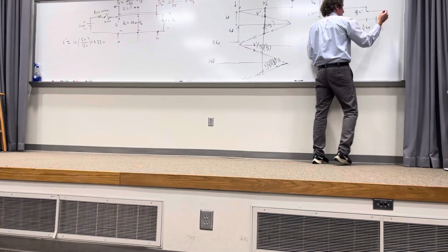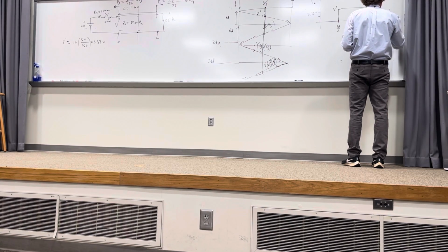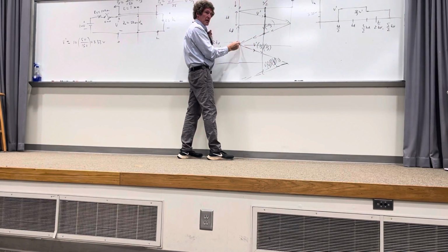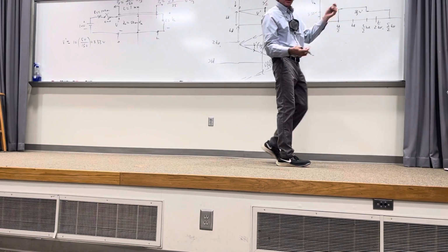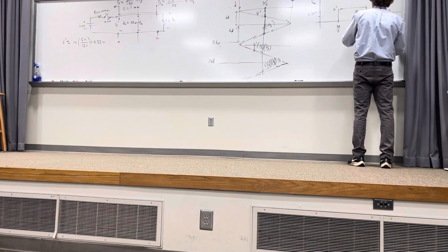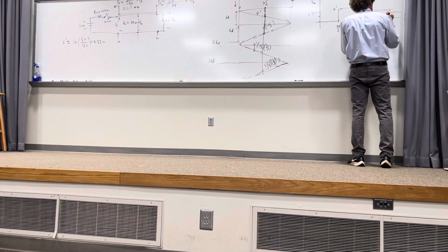And it's going to stay there for how long? Until I hit what? 5/2 TD, correct class? And then what's going to happen? Let's take a look. Comes down here, hits here, right? Now, the wave that it interacts with is this wave, right? Which is going to be -1/3 times 1/3, or -1/9 V prime, so it goes down again. Do you all see this? It's going to go down again. So now it's going to be 2/3 - 1/9, so that's 6/9 - 1/9... actually 2/3 is 6/9, minus 1/9 is 5/9. Wait, as said: 4/9 - 1/9 is 3/9, so it's 1/3. So this would be V prime right here over 3, and it's going to stay there.